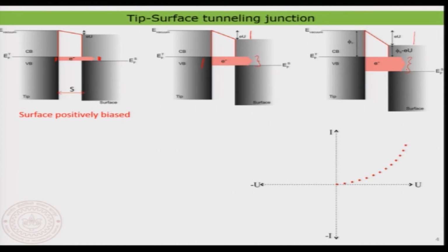It is looking more like a curvy nature for a constant density of state. So, that is quite important. We will come to that. That is also the reason why I have taken a constant density of state, and you see nicely that the current increases as the voltage increases. Well, you would somewhat guess, because I also have to consider the so-called tunneling probability, that exponential function is also now weighted inside the current. In the ohmic contact, if you recollect what we have done in the previous slide. Now, that is quite interesting.